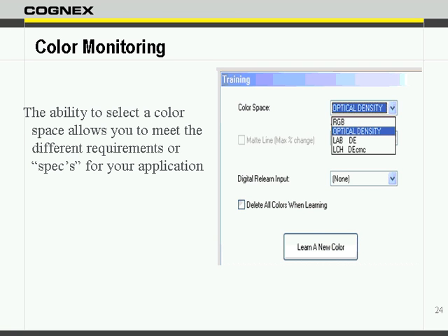So this is what we were talking about just a minute ago in terms of color spaces. Red, green, and blue is the main color space. This is the color space that the camera acquires images with. It's a CCD with red, green, and blue values. We have other color spaces that are available. It is important to know that these color spaces are always calculated from the red, green, and blue, because this is what the camera detects to begin with through physical means, through the optics.